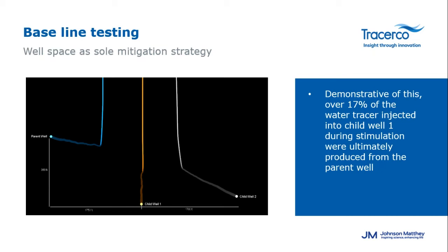As a mitigation measure, the parent well was shut in and allowed to naturally build pressure from the formation. The results indicated the furthest child well communicated approximately 5% with the tracer applied to well 1A, to the infill well 2A. This suggests there was enough well spacing between the child wells.